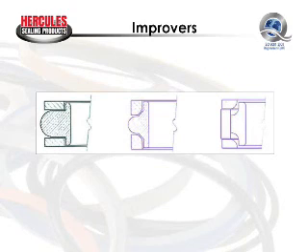T-seals were originally developed for the aircraft industry, where they were used in landing gears and control surfaces on aircraft, the actuators that control the control surfaces on aircraft. They operated at a lot higher pressures than O-rings because of the built-in backup ring and the extra stability designed into the seal by the flat back.